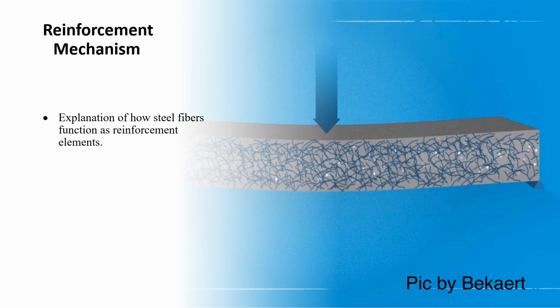In traditional concrete, which is strong in compression but weak in tension, the addition of the steel fibers helps distribute forces more effectively, resisting cracking and improving the overall durability and strength of the material. The fiber acts as a reinforcement to hold the concrete together, especially under conditions where tensile forces might cause it to crack.